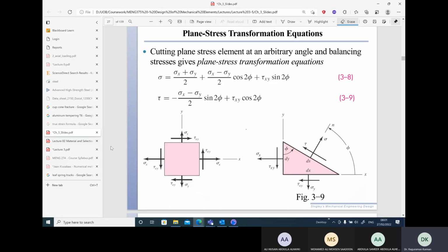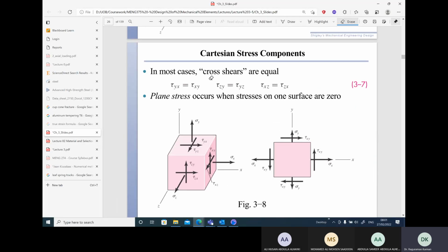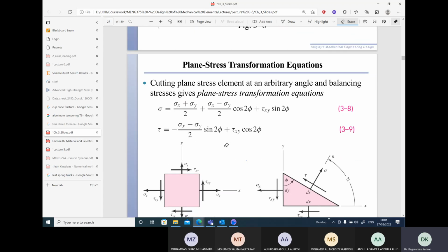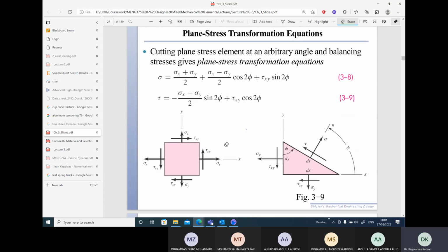Okay, last class we stopped right here. That's the previous slide actually. We proved that the stress tensor is symmetric, and we also showed that there are 6 independent components, and we also figured out how to find the signs of the stress components. So today we'll see how to calculate in 2D and later 3D, how to find the eigenvectors and eigenvalues.